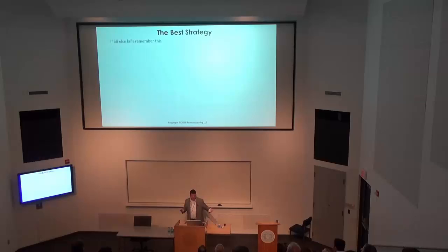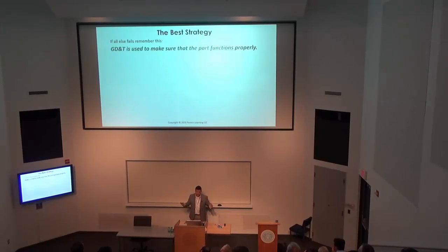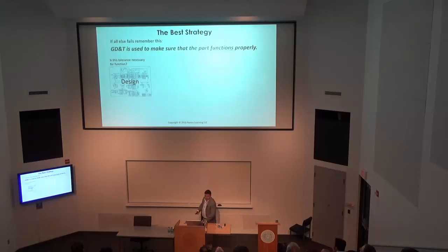So the best strategy, if all else fails, remember this. It's what everyone's been telling you this whole day. GD&T is used to make sure the part functions properly. If you can remember that, and that's the only thing you remember from today, that's perfect. That's all you need. From design, you should be asking yourself, is this tolerance necessary for function?